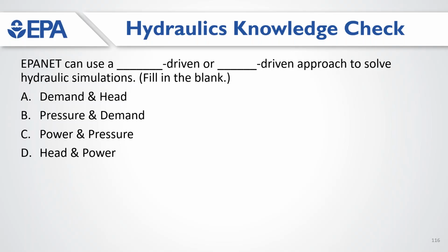Okay. The correct answer was pressure and demand. EPANET can solve hydraulic simulations using a demand-driven approach, DDA, to compute pressures and flows, or a pressure-driven approach, PDA, if there are pressure-deficient conditions. Hopefully most of you got that right from what we just had you do.